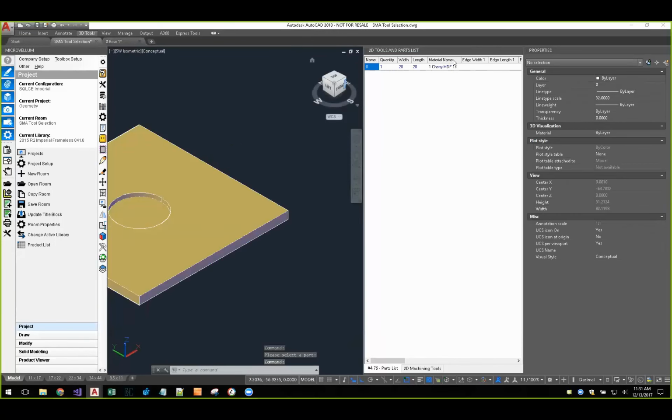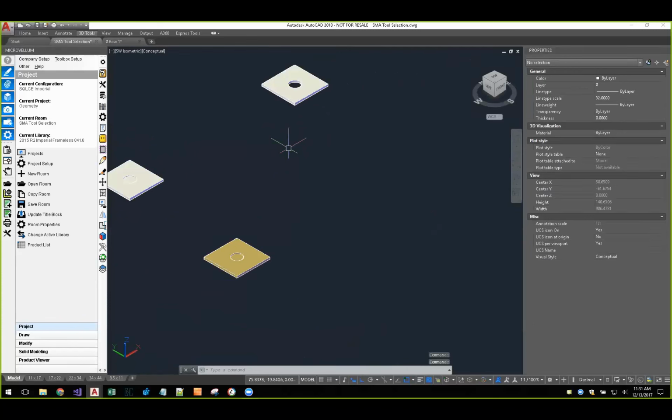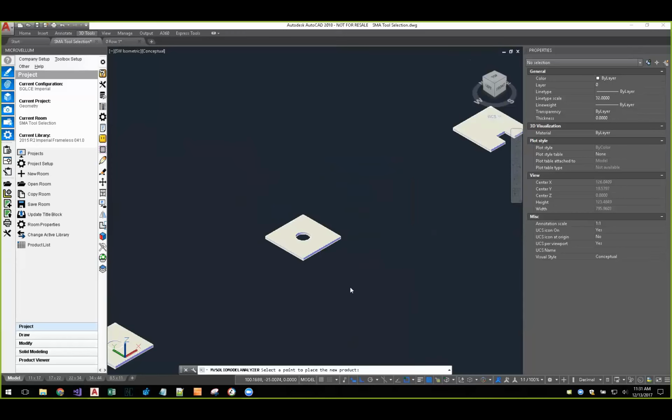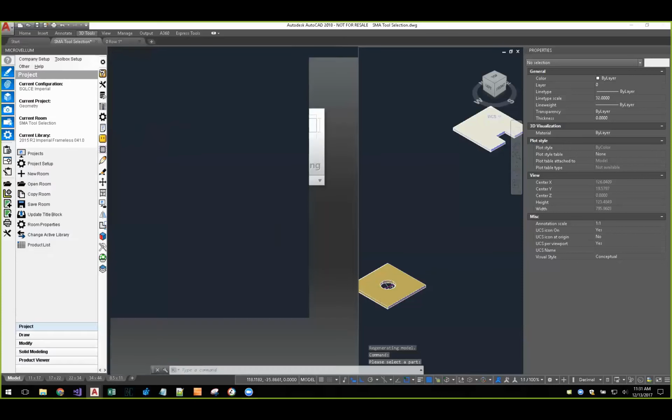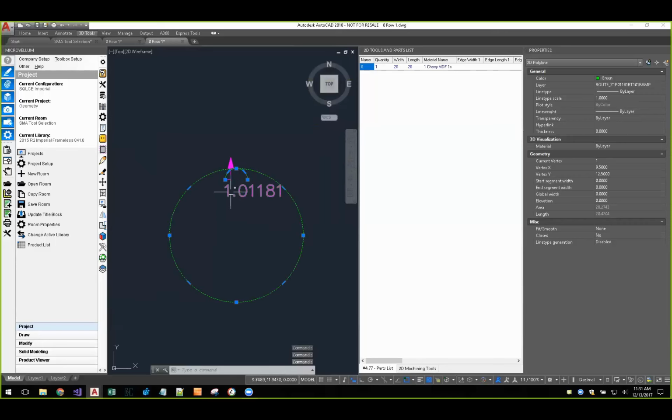So let's see, this toolbar is kind of in my way for the meeting. Okay, so let's take a look at our next part. This one is actually not a pocket, it's a cutout. So we'll analyze that. And then we'll draw it to see what kind of machining the algorithms came up with. And so it automatically created our lead-ins and lead-outs and everything we would need there, ramp lead-ins, and it's using tool 101. So I won't take our time to open the tool file again, but that's what we specified as our default router.